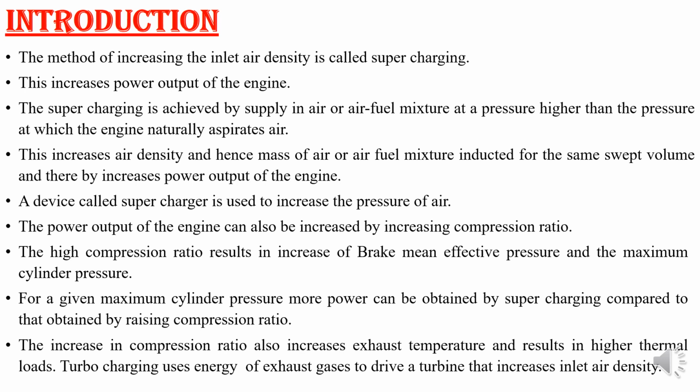Whenever supercharging is done, it also increases the compression ratio and the exhaust gas temperature, which results in higher thermal loads. But turbocharging, which will come a few slides later, uses this exhaust energy and increases air density, which reduces your thermal load. So this is about your supercharging introduction. Now we will go for the forced.